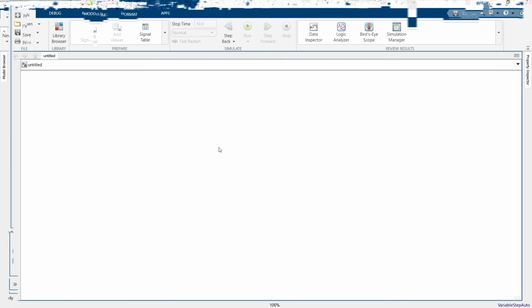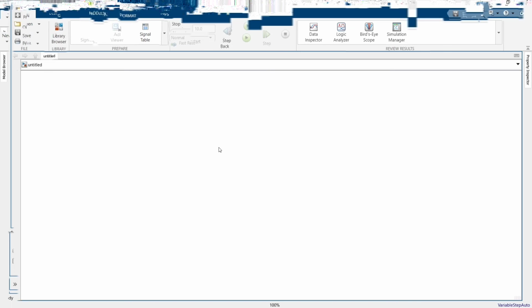So I'll call a bus selector. This bus selector is used to select the signals from my components. So I want the SOC output of my battery and I want to plot it. I also require some more outputs to visualize. So I'll go for 3 outputs, and I will select how to plot them. I have selected how to plot. Then after that, my current output and my voltage output.